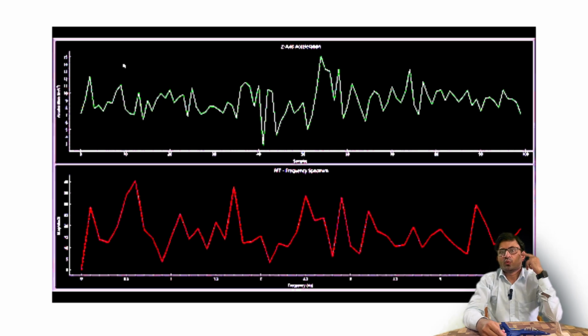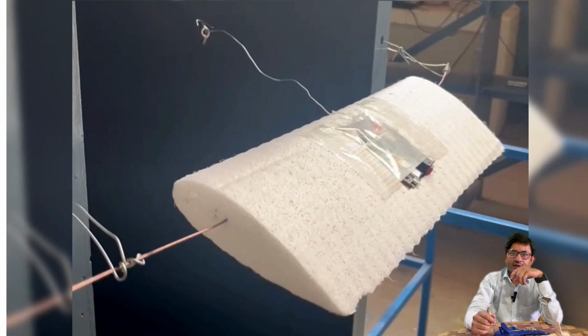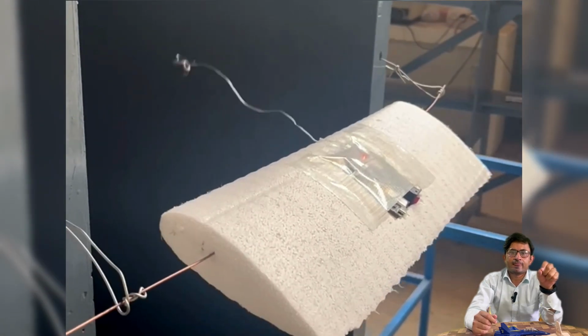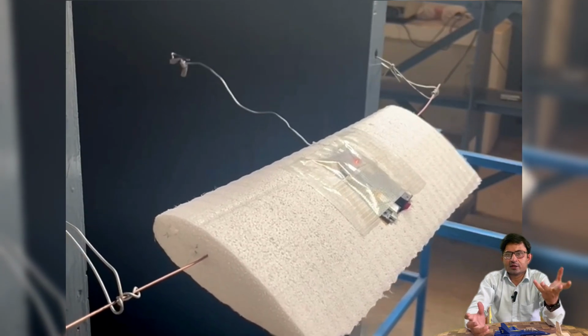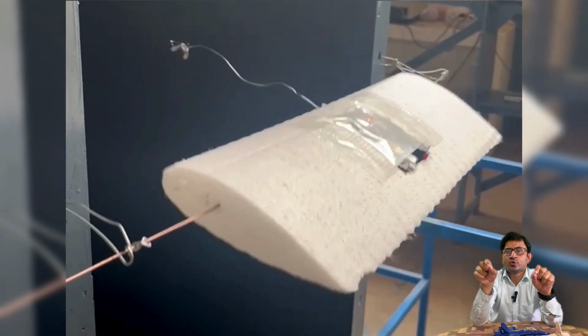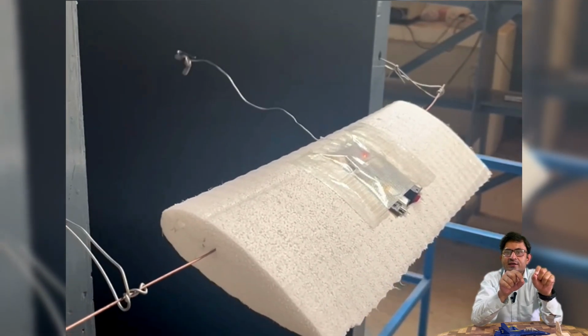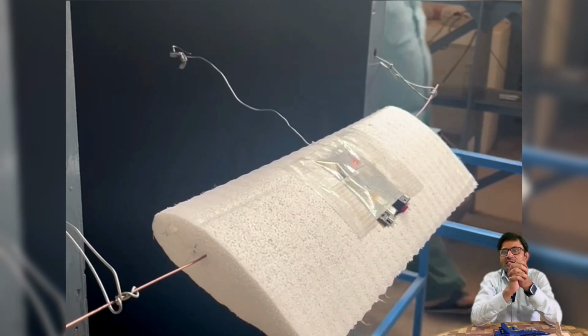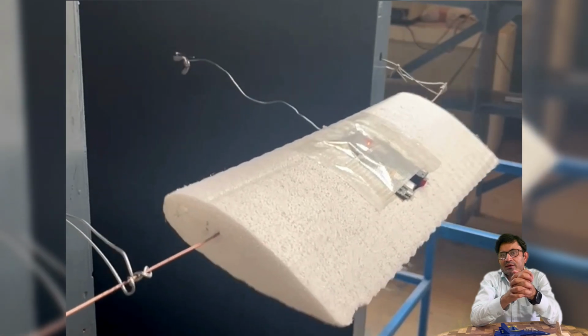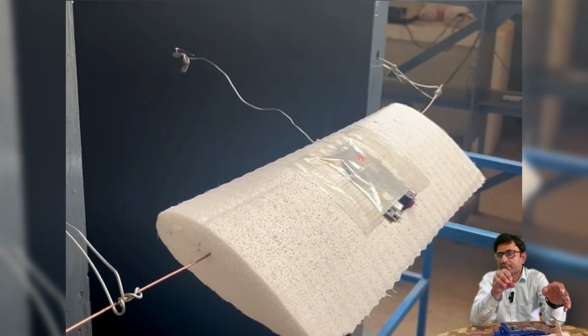So what we can do here, we can put a small mass, or the required mass depending upon your setup, in order to move the CG towards the hinge line in order to reduce this kind of phenomenon. In all aircraft, it is important to do mass balancing.